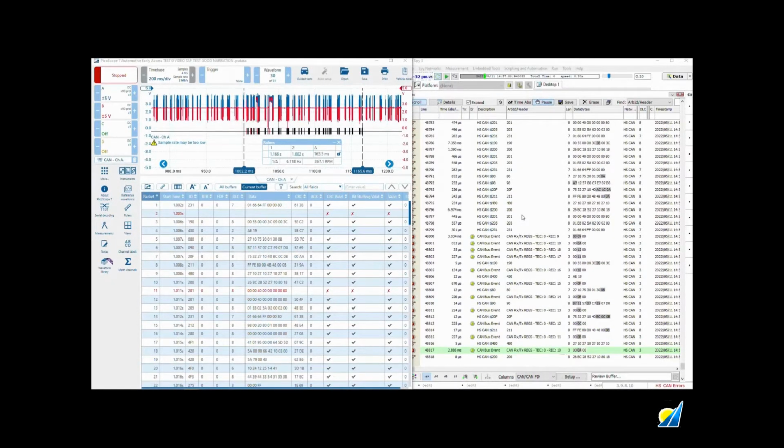A bit more information about the error counters within the CAN controllers. We saw here that 231 was the last message that got through. Then we had these errors here, and note the error counters start to increase as we described. The fact that these are green suggests that the error is active. In other words, the node is still allowed to participate, still allowed to communicate on the network, flag errors, and terminate messages that it feels are in error.